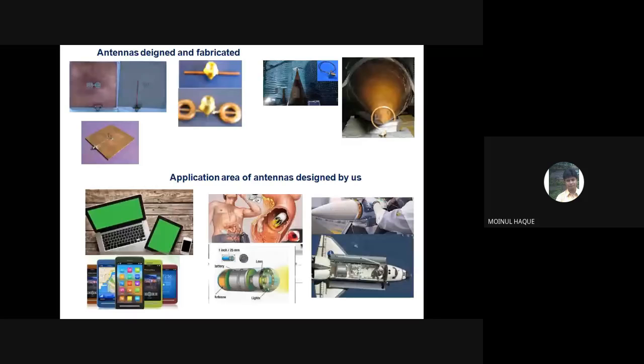Okay. So the antenna which we have designed, antennas can be miniaturized in many ways. The conventional process is that we increase the length of the antenna, by using metal, using a spiral, or whatever way you can increase the length. The second is either using inductive loading or capacitive loading. And the third is the use of metamaterial. So these are the commonly used techniques for antenna miniaturization.